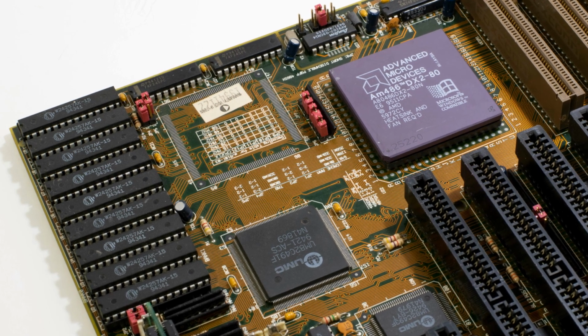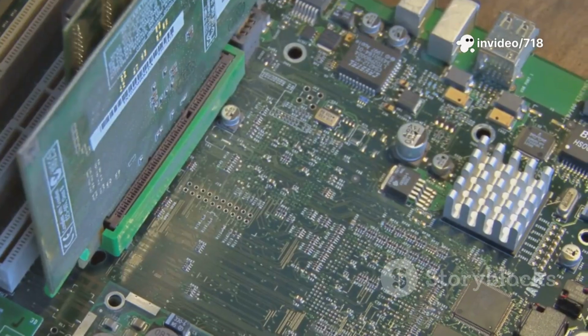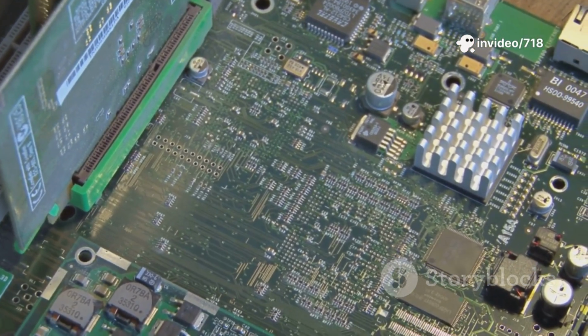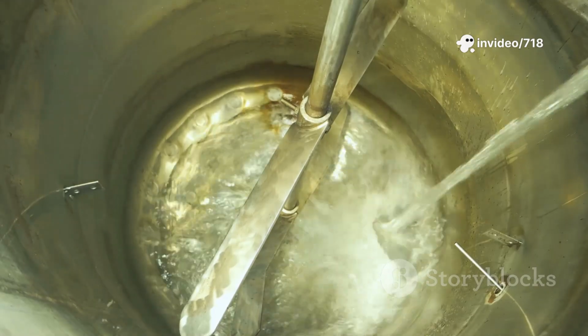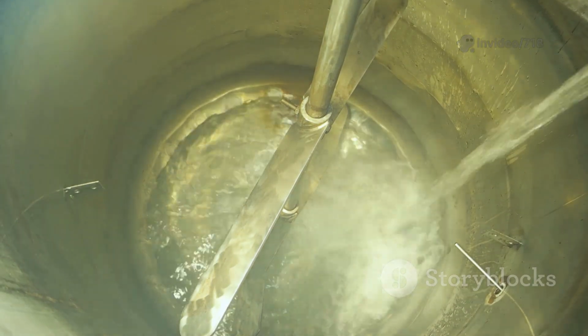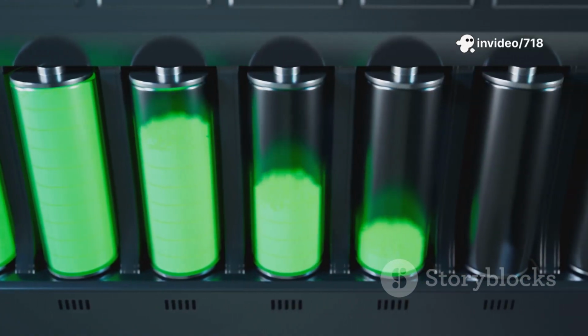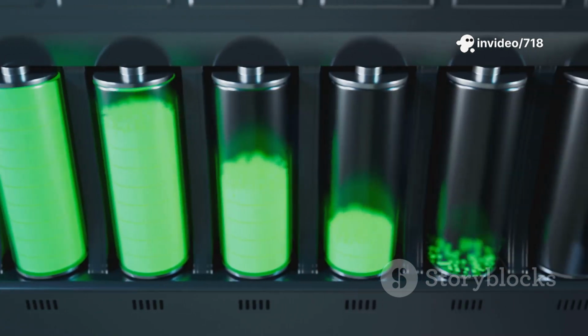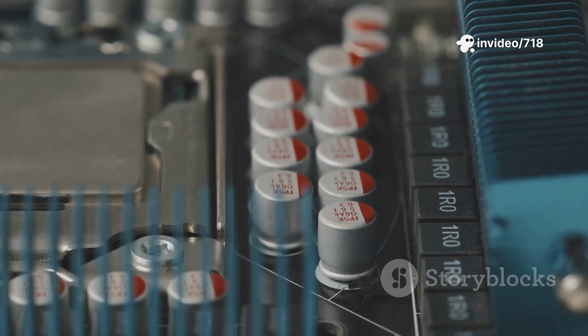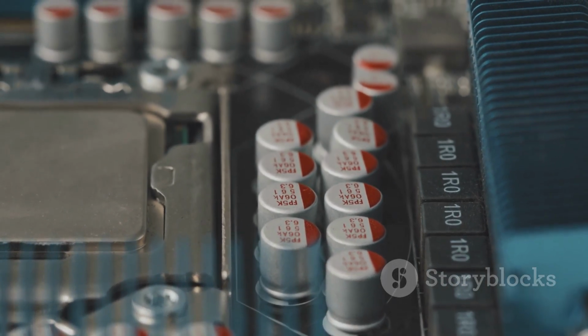Now, here's where the dynamic part comes into play. These tiny buckets, these capacitors, are not perfect. They have a small, unavoidable leak. The electrical charge that represents your data slowly seeps away, almost like water evaporating from a bucket on a hot day. If left on its own, a full bucket, a 1, would eventually become empty, a 0, and the data would be lost forever. This leakage is a natural characteristic of the components used.